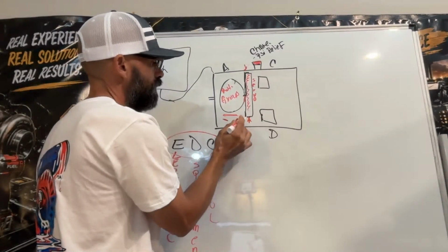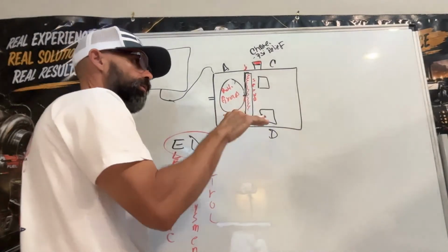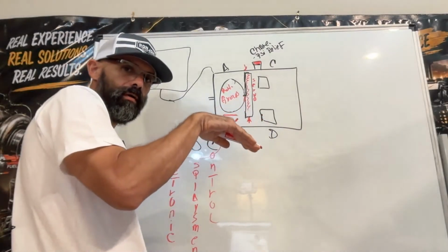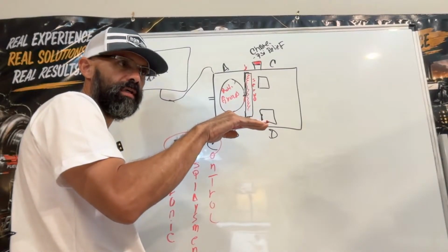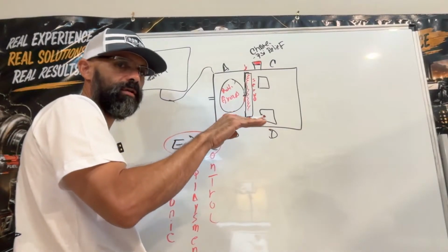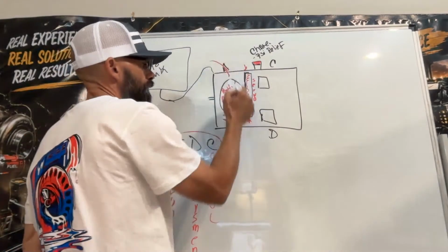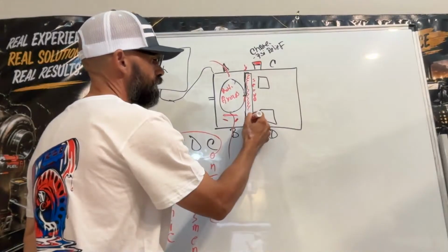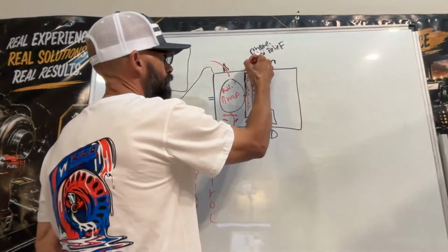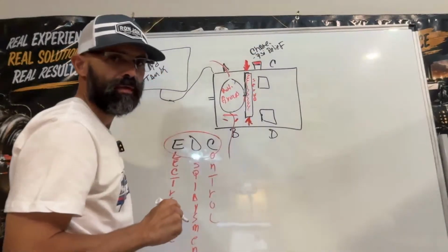Or the other ways. So you're gonna have an inclination. It can go from here to here, right? And then back to neutral if you let go of the joystick. And then if you go the opposite direction, it's gonna go like this, right? And that's what sends either pressure to A or to B, depending, right? Because this thing is gonna be moving a certain direction depending on the movement of your joysticks.